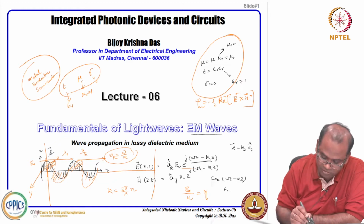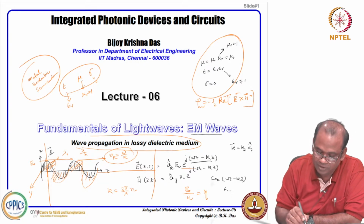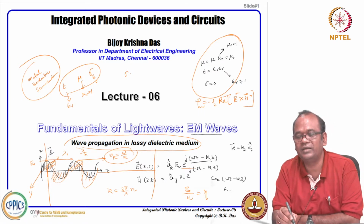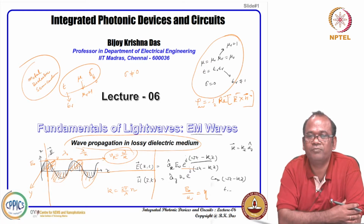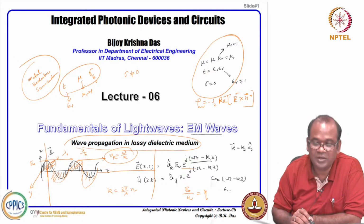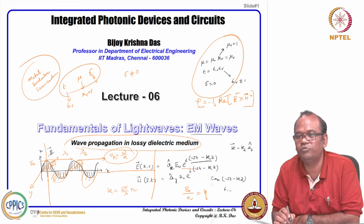In that case, no loss is there, as we have discussed. Now we will consider a wave propagating in a lossy dielectric medium. Where we considered ideal dielectric, sigma was equal to 0. Now we are considering that it is not really an ideal dielectric, but sigma is not equal to 0. In that case, this is not an ideal dielectric. We would like to see whether the presence of sigma can hamper the propagation of the electromagnetic wave or not.